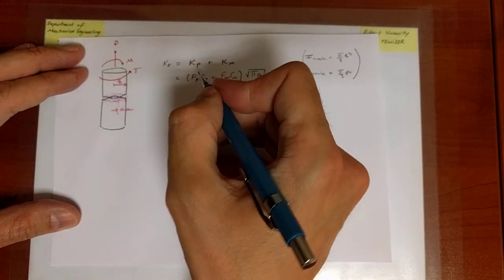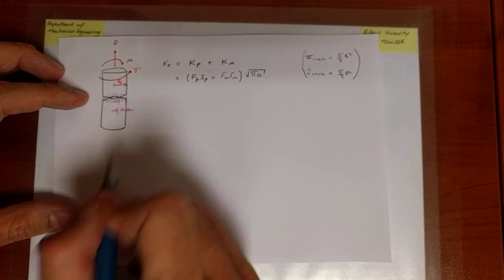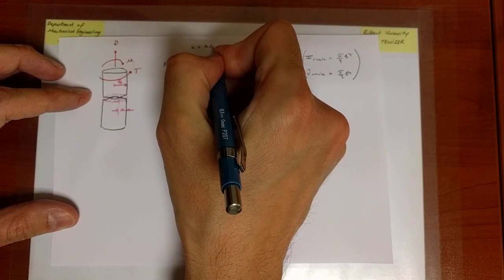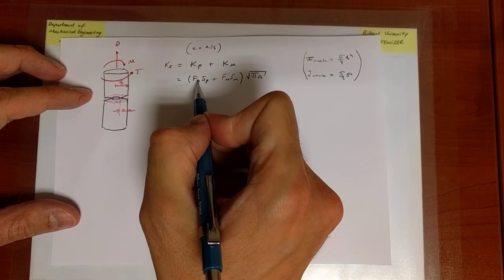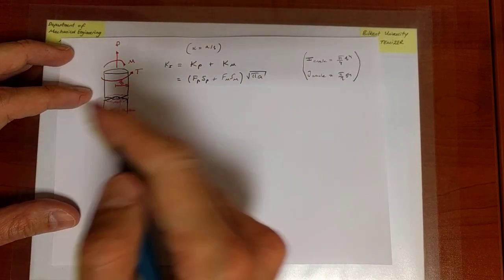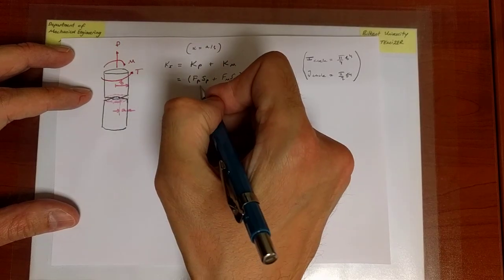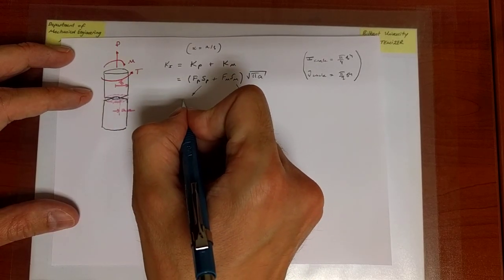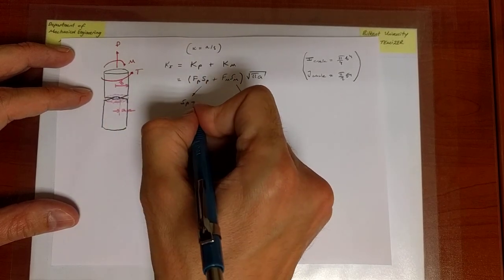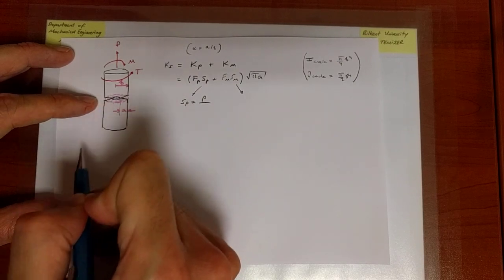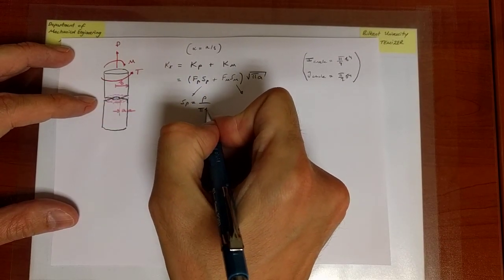And you can remember, so first of all, F_P, the value of alpha in both cases is equal to A over B. But the functional form for these two can be different. In general, it is different. So I need to look up the tables in the book to understand what they exactly look like. But what I should remember is how to calculate the gross stresses. At the cross-section where the crack is present, omitting the presence of the crack. So it's the load divided by the area of the cross-section, omitting the presence of the crack. So it's pi b squared.